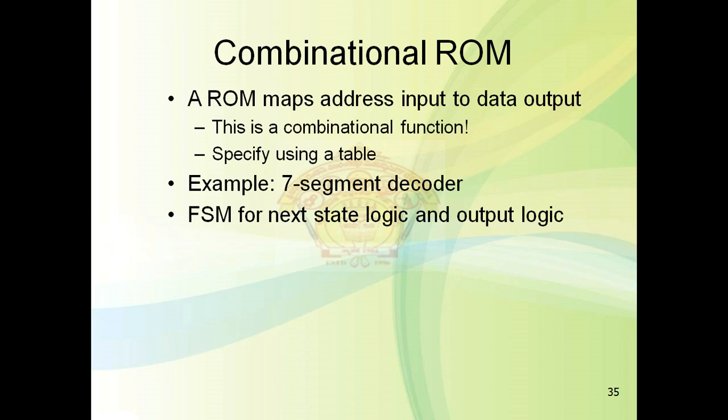you can see, is the 7 segment decoder that we have discussed. There we used the input data as BCD and one more blank input, and we give the decoder output to the 7 segment display. So we require fixed code words for it. If it is 0000, that is for 0, so you require the 4-bit data, and one more is the blank input. So that is 5 inputs, and we will require 7 outputs for the 7 segment, because you will get the 7-bit code word for it.